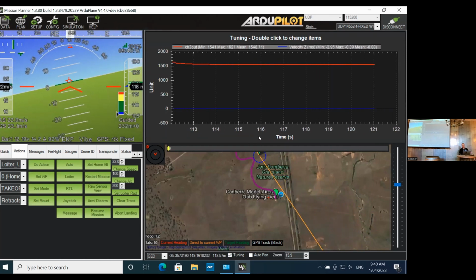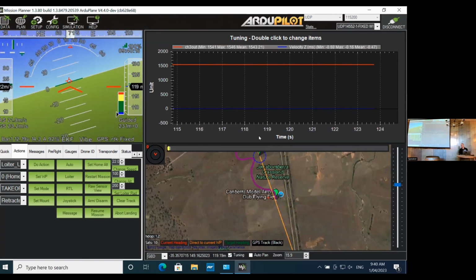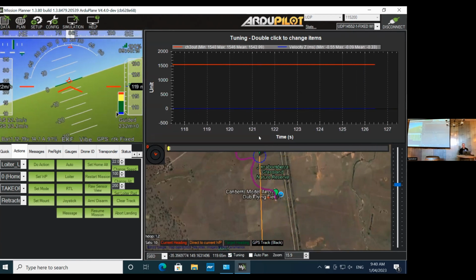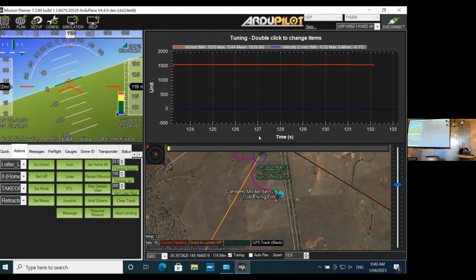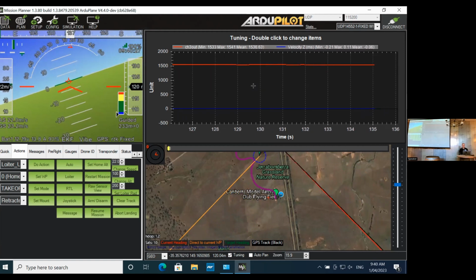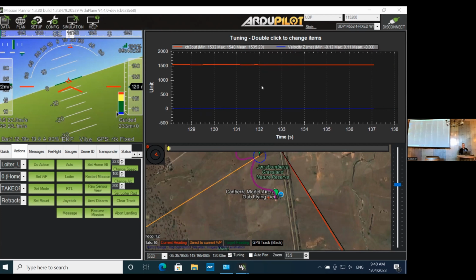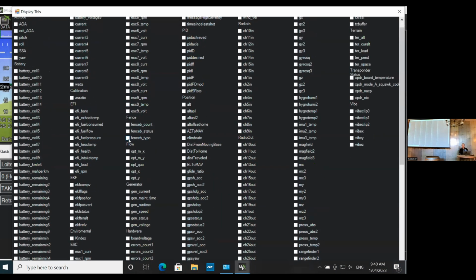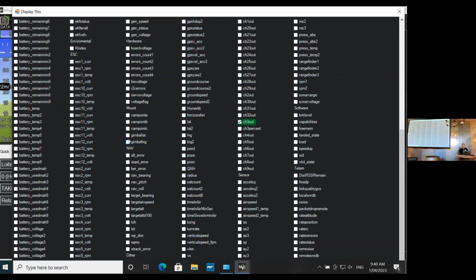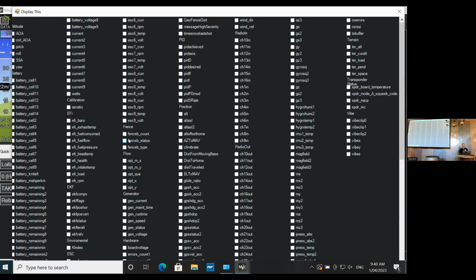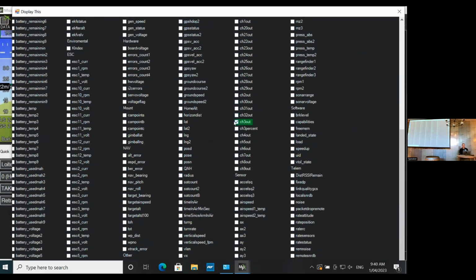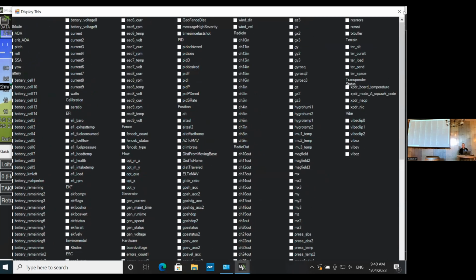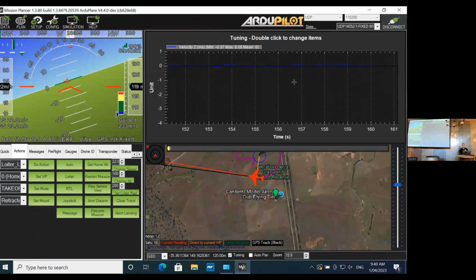Unfortunately at the moment, to monitor throttle, you have to monitor the servo output. I wasn't able to find on the MAVLink the actual throttle. VFR throttle is valid? Okay. It's there somewhere. We need a search, Control-S search in here. All right. Anyway, I'm going to monitor the climb rate. So take channel 3 out, get rid of that. We do have climb rate. Velocity is there.